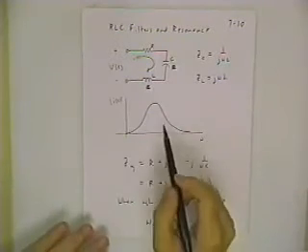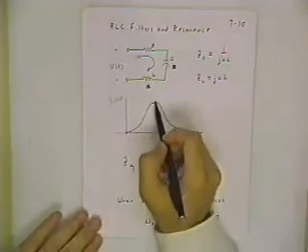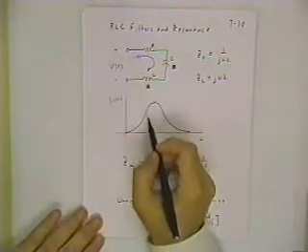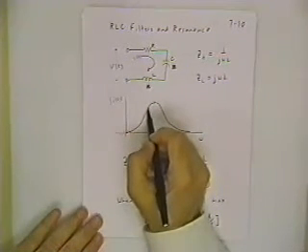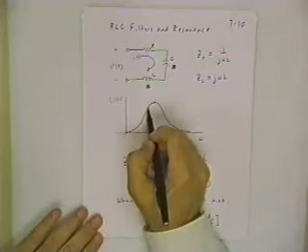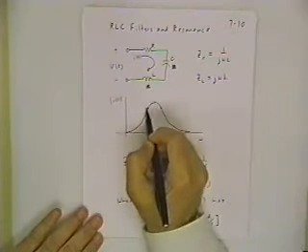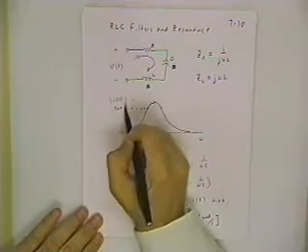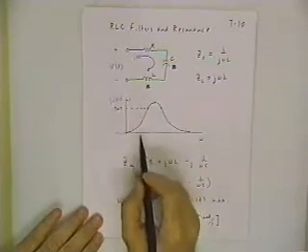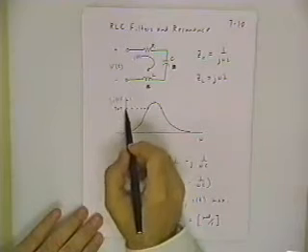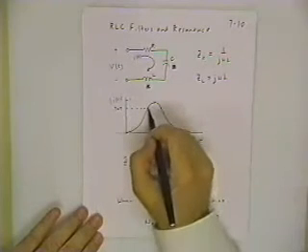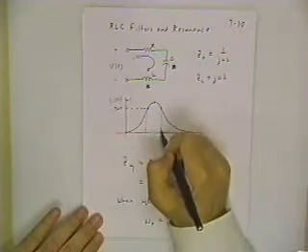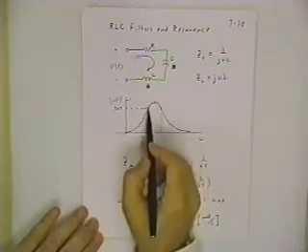Now before we leave that, there's an aspect of this resonance curve, it's called. It says if I look at the half power points, and half power means that I'm looking at 1 over square root of 2 of the magnitude. So if this is normalized to a value of 1, and I go down by a factor of 1 over square root of 2, that defines a range of frequencies over which we have pretty good transmission.